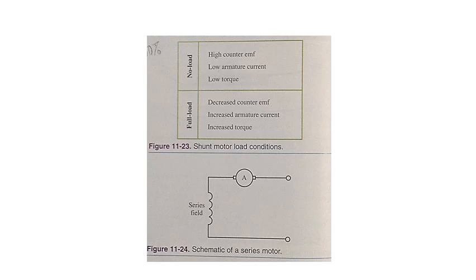All the line current must flow through both the field and armature windings. Under loaded conditions, the counter EMF opposes the line voltage and keeps the current at a safe level. If the load were suddenly removed, the armature would speed up and develop a higher counter EMF. This higher counter EMF would reduce the current flowing through the field and reduce the field strength. In turn, the motor would increase its speed because of the following formula, where speed equals counter EMF divided by field strength times K.